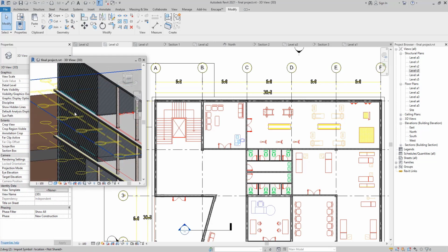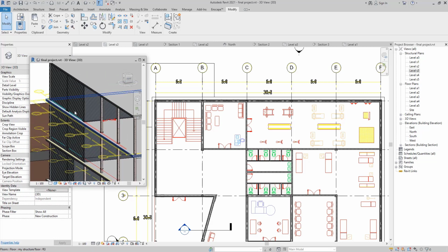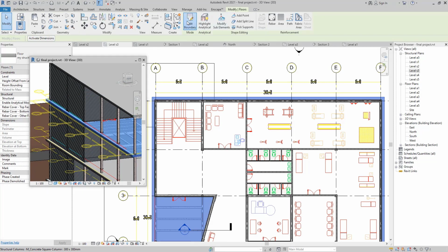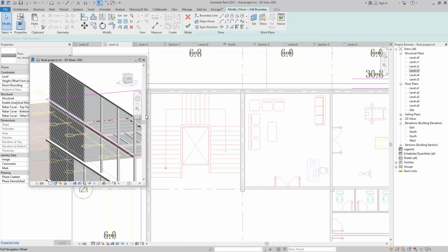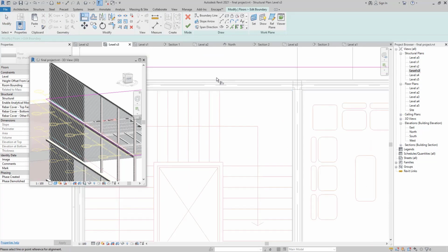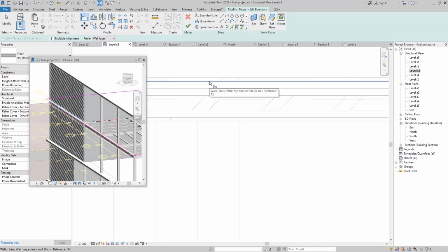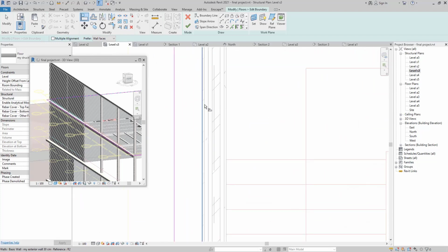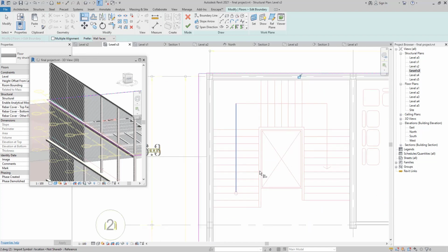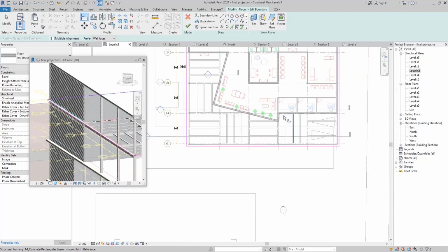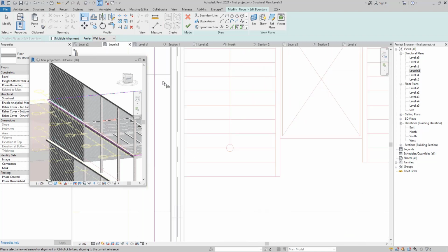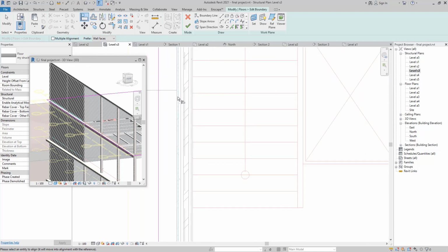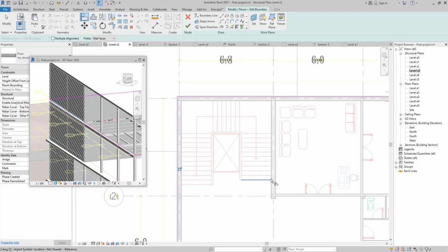After that, I'm able to see what I'm going to do. So I'm just going to click my floor here and edit boundary. The next step is to use the align option and click align to this line. You can use align, or you can simply use, for example, the drawing option, but since it's just a few edits, align makes more sense.